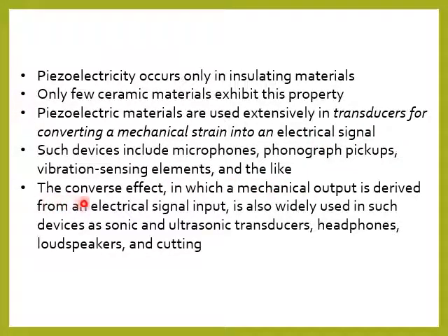And the converse effect, the opposite effect, is for reverse piezoelectricity. Mechanical output is derived from an electrical signal. We apply an external electric field, and mechanical distortion takes place, and it is used in such devices as sonic and ultrasonic transducers.